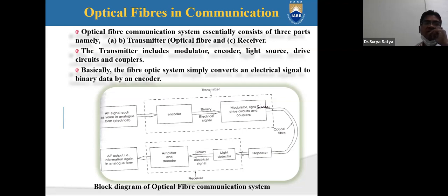There is another kind of step-index fiber, the multimode step-index fiber. Here the diameter of the core will be a little larger than the single mode step-index fiber, and it varies significantly. As I said, the typical value is 62.5 micrometers, but you can have from 50 to 200 micrometers. The diameter of the core will be 50 to 200 micrometers.